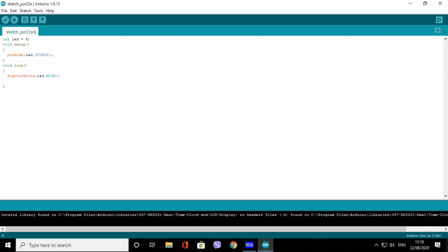Now go down. We have written digitalWrite LED HIGH. Now we will have to write that it will stay on for 1 second. So the time will be written in this format: delay, delay means time. After delay give a first bracket.